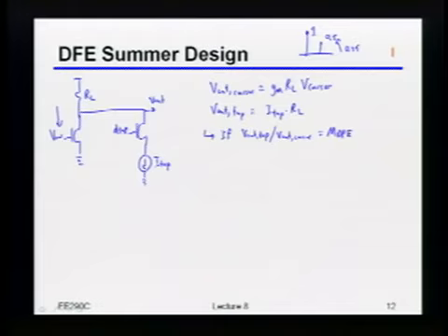And then basically the size of the switches that I'd have to use would all be proportional to that relative amount of signal that you're canceling. Does that make sense to people? Or in other words, if the sum of the absolute values of the ISI afterwards was, let's say, 5, then I would use an MDFE of 5. Okay, meaning 5 relative to the cursor.